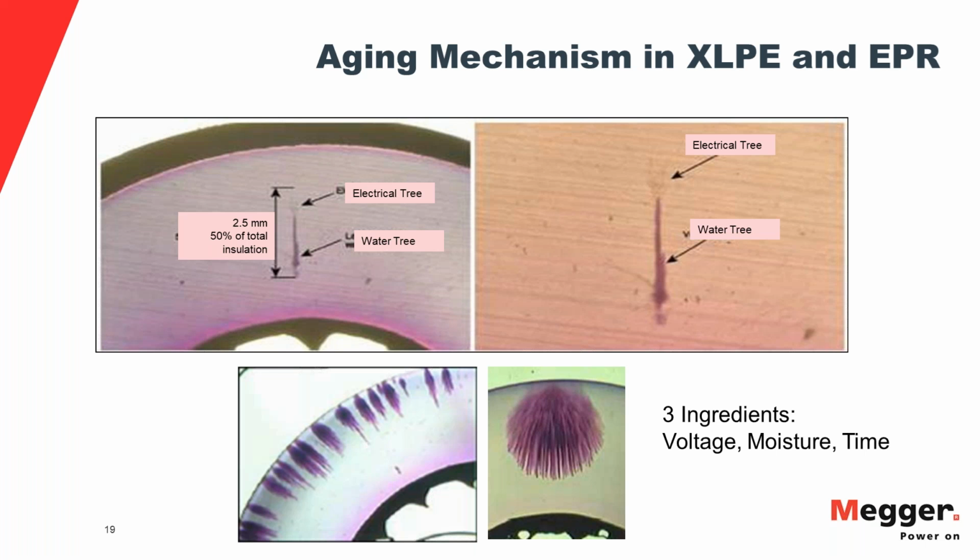In some cases, when you cut the cable open, you can see maybe small white dots along the insulation, but that's pretty much it. And if you cut it back and the insulation seems to have, you can look through it and you see these few white spots, then it's already contaminated and in a very bad condition anyhow. But these are these treeing phenomena.